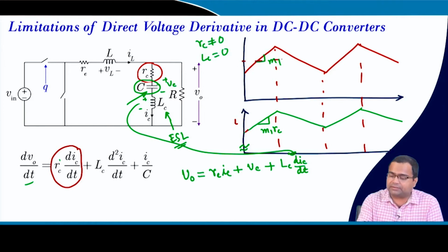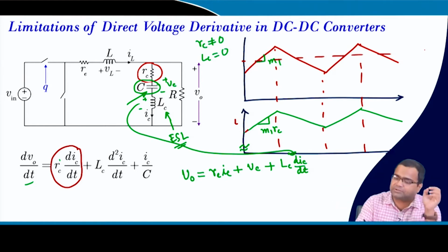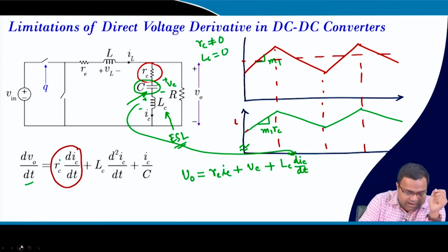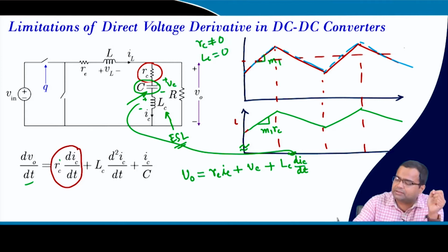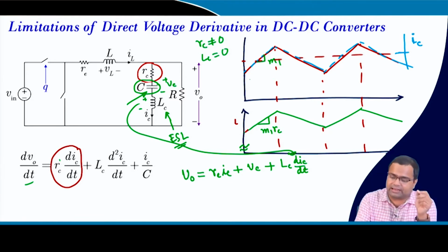The capacitor current, if you remove the average current, will be similar to a triangular wave, but it has a 0 average. So, this axis is my capacitor current axis. Now, if we take the derivative, here you will get a positive 1, negative 1, like this, and this is due to this term.